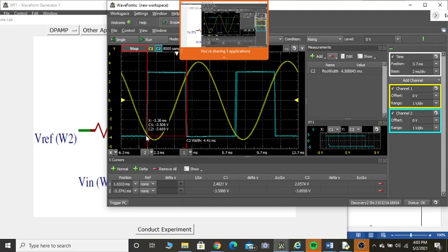What is this voltage here? C1 is minus 3.6, minus 3.5. Output is having a transition from minus VSAT to plus VSAT. So what are VTH, VTL now? VTH is 2.4, whereas VTL is minus 3.5. Correct? Okay.